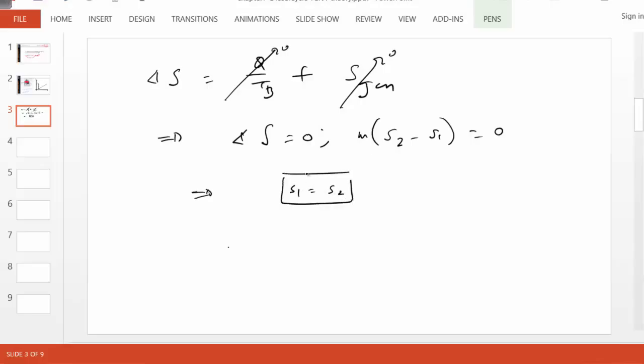As soon as you know S1 equals S2, we can apply the PG model isentropic relationship, equation 11 of the PG model. Again, you must be familiar with this from our Otto cycle discussion. Table J has all these equations listed.